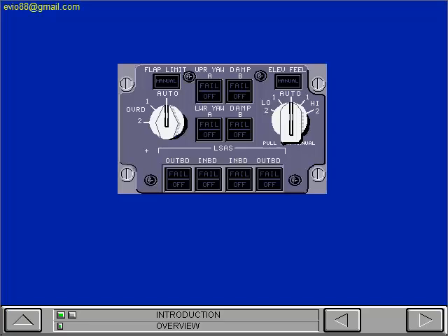The controls and displays on the AFSCP are 4 longitudinal stability augmentation system off-fail push-button switches and off-fail lights, 4 yaw damper off-fail push buttons and lights, a flap limit override switch, a flap limiter system fail light, an elevator feel knob to make a selection of low to decrease load feel and high to increase load feel.